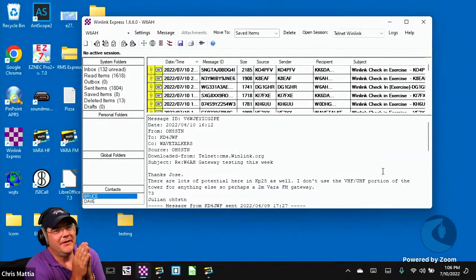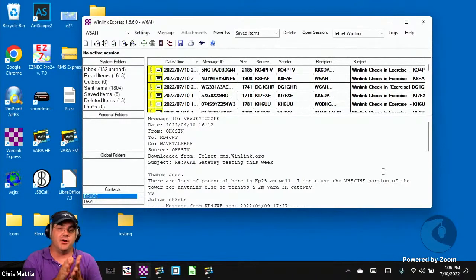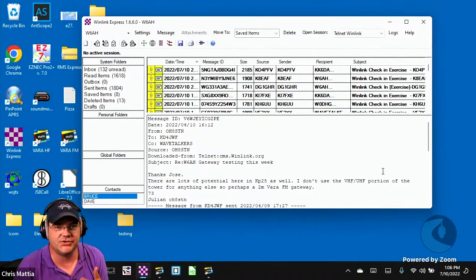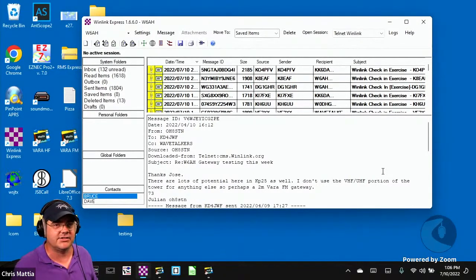All right, so we're out on the beach this week and we're doing some Winlink traffic. However, you want to make sure before you head out to operate that you update the propagation tables and you update the server lists for whichever mode you're planning on operating. And you do that from inside of Winlink. Now, you do need to have your radio connected to your computer that you're going to be taking out into the field with you, and make sure that it's all connected, everything's talking.